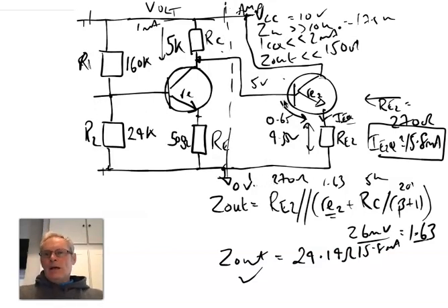Now the ideal solution would be to design probably a class A voltage stage and then put it through a push-pull amp, so it becomes class AB. And by doing so, we put two transistors in series. One is going to switch on during this phase and the other is going to switch on during this phase. Obviously we'll get crossover distortion, but we can mitigate that with a few other design tricks.